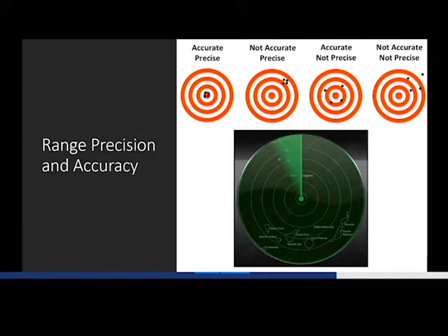In radar, measurement errors are due to a combination of many factors, including interference such as noise and clutter, target phenomenology such as glint and scintillation, signal propagation characteristics such as multipath and turbulence, system measurement limitations such as signal quantization and signal sampling rate, and system uncertainties such as gain calibration, channel-to-channel phase calibration, and antenna pointing errors are all error sources that can impact both the accuracy and precision of the measurement.